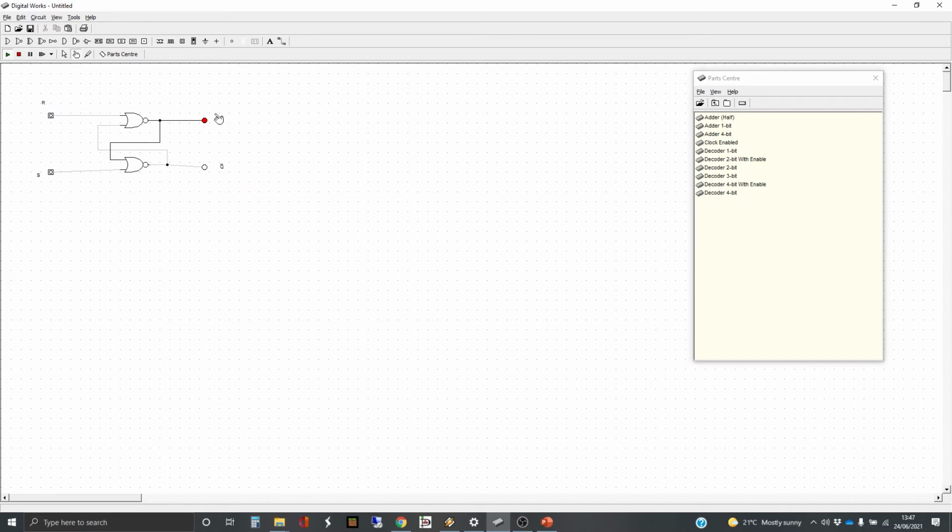To reset is when we're going to set Q to low. And generally, we become interested in one output rather than having both outputs. Both outputs are available, but we tend to use as a data store this, set it to high using S and set it to low using R. So that gives us a low at Q. If we do it again, nothing changes. If we do it as S, it changes back so that Q is high. Okay, so this particular circuit is called an SR latch. A latch means that it will switch one way or the other way, and it's bistable.